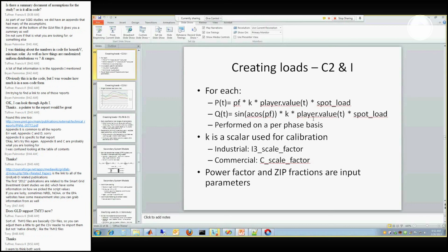Okay, and we don't have to worry about the positive sequence 120-degree offsets between phases. You take care of that. We just give you power factors or relative angles. Correct, yes. As long as the swing node is set with your 120-degree shifts, then all the rest gets solved. But when you're looking at your load behavior, if you're using constant power or constant impedance type of loads, they automatically adjust.